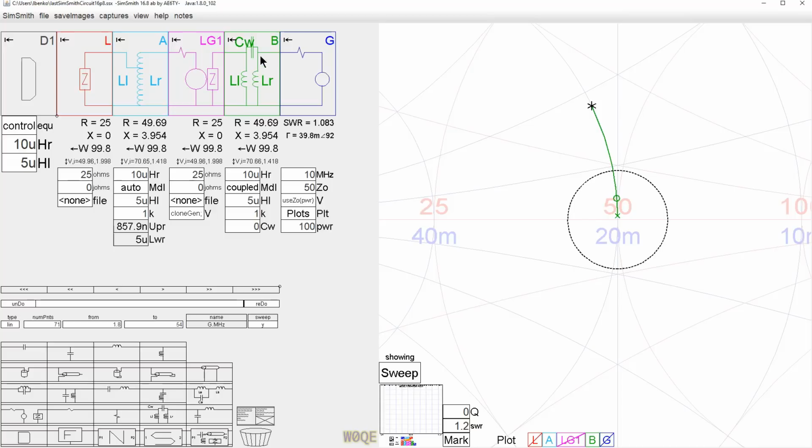Sometimes you need to have maybe a DC voltage on one side of the transformer and the other side is some kind of a generator that can only source current or sink current or whatever, and you need the other side to be connected to ground. If you need to do something like that, you cannot use an auto transformer and you're stuck with a conventional transformer. However, in many cases, or maybe even most of the cases, an auto transformer works just fine. You don't need that isolation.